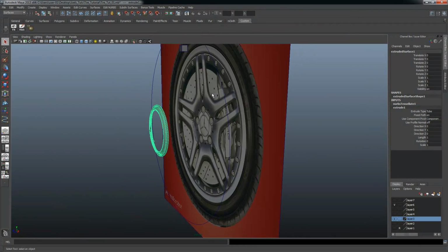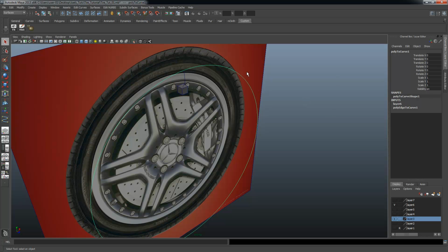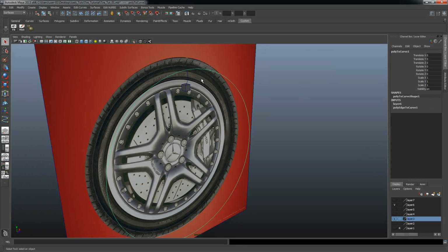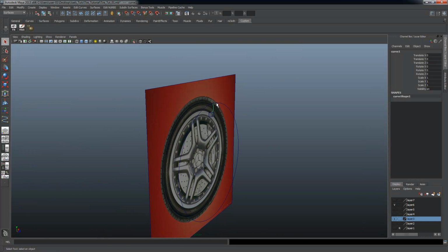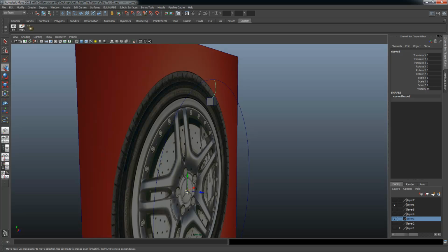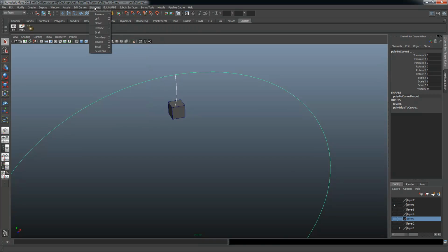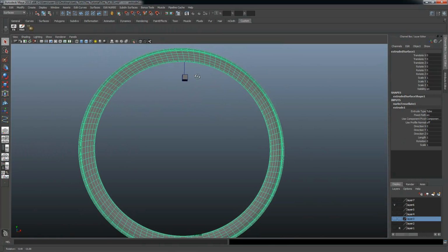And the scale is off. So I want to figure out what's going on there. Let's select my mesh here. Is it that? Oh, the reason for that is because my profile curve that I just drew for my sidewall, its pivot point is down here at the origin, and so what I need to do is move the pivot point for this guy so that it is right on the line. I hope this is it. That was it. Okay, that's one.